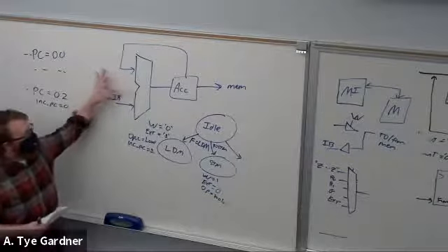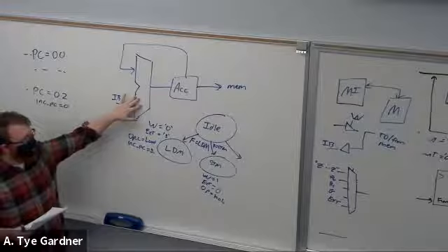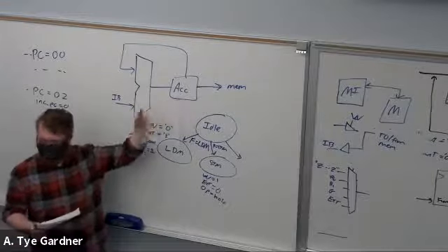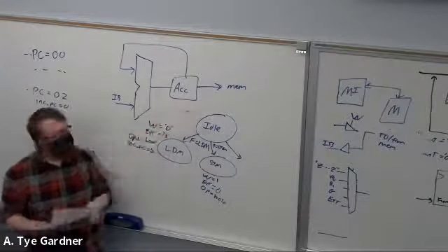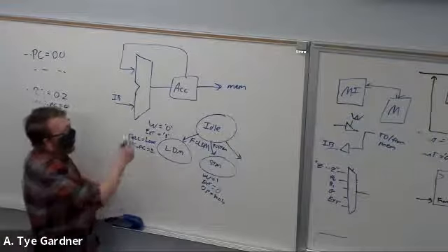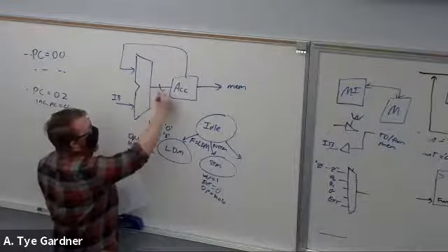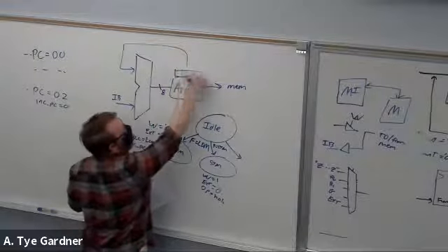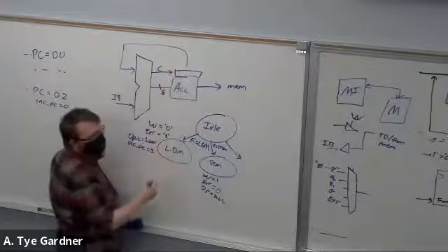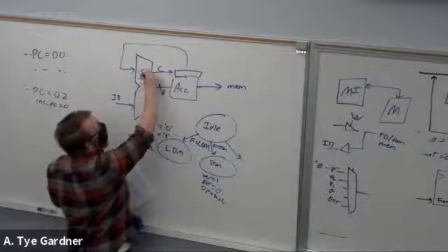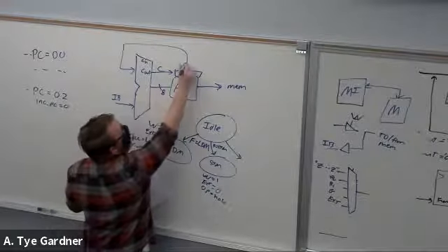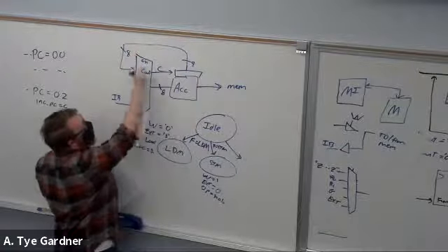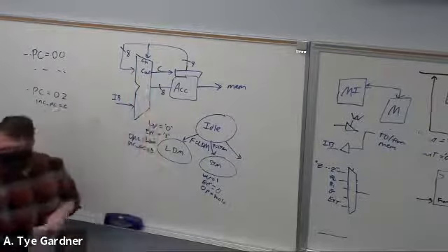So the ALU and our accumulator, I'm going to go through this real quick. This is pretty self-explanatory. This is just a register of D flip-flops, right? A couple different ways to do it: this can either be 8 bits, and then you'd have an extra for the most significant bit that is carry, the carry out, C out. That makes this 9 bits, this 8 bits in the feedback, and we just tap one out to go into the C, right?